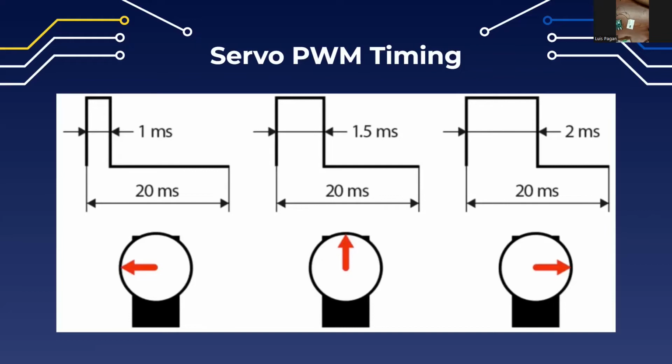So you have a range of really 10, and that will get you the full 180 degrees on the servo. These servo motors only rotate 180 degrees. There are some servo motors that are continuous, but for this application we don't need continuous servos, because otherwise it really just becomes a motor with finer control. So we'll be using 180 degree servo motors.